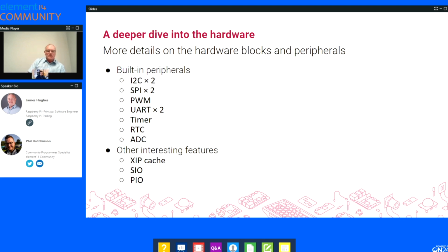Right, the ADCs, the analog to digital converters. We have a single analog digital converter which is muxed over 5 inputs. 4 of those inputs go out to the GPIOs, on I think 26 to 29 or something like that. One input, the 5th input, stays internal to the device because it's attached to an internal temperature sensor. So effectively, we have 4 inputs, 4 ADCs.